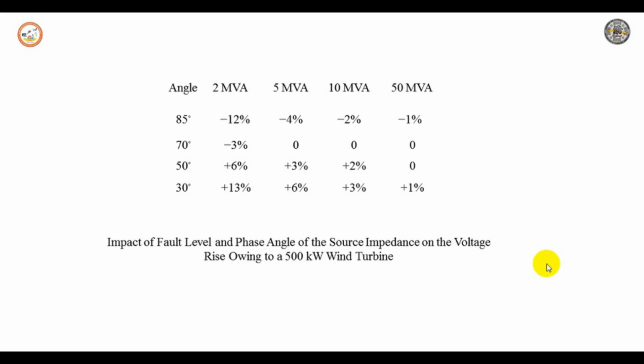So the voltage variation on a low voltage feeder in Manchester, UK, which is currently supplying 69 homes, each equipped with a 1 kilowatt micro CHP unit. The feeder was specially designed to cope with a large amount of distributed generation, and a 330 mm square cable was used as a precautionary measure instead of the 95 mm square cable they were using earlier.